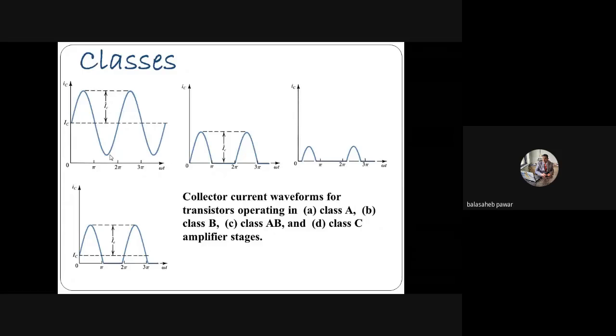Okay. Now see, but in general we are considering the output of such type of amplifier as an AC output. Correct. So how will it be possible? It is possible only by using the output coupling capacitor.